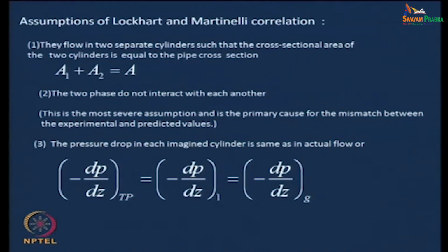This was a very serious assumption, and we will see that shortly. In fact, in the last class I had tried to apply the separated flow model after deriving the analytical expression. What I tried to do was find phi L square for annular flow by considering the actual flow circumstances and the Lockhart-Martinelli correlation, and I wanted to show you how well these two expressions agree. I could not complete it, I will be completing it.